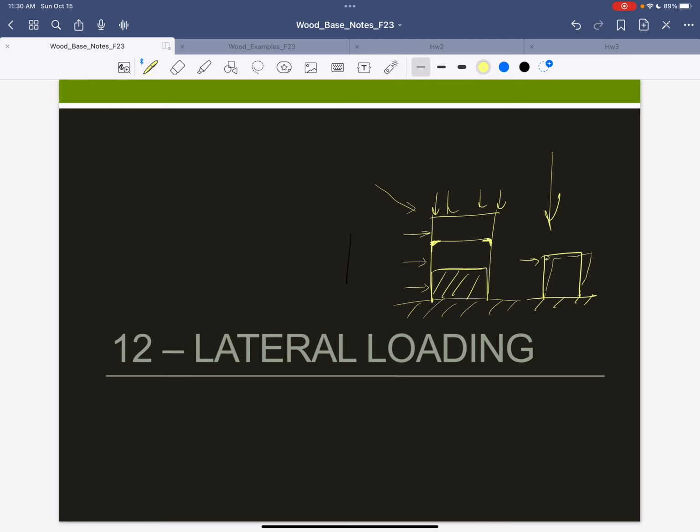And that wall, if I look down on the building, so I'm looking down on the building now, just at column grids or what have you, right? So when I look down on the building, if I'm pushing from this direction, it's this. I could put a wall in here, maybe by the elevator shaft, and you will go through this stuff in your senior design to some extent because you have to have something to hold the building up laterally.